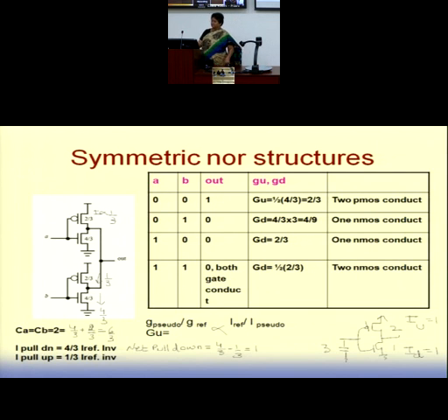In this case, they have chosen the values to be nearly the same as pseudo NMOS just to show that it works over here. So if it is taken as 2/3 and 4/3, and this is also 2/3 and 4/3, we are deviating from mobility ratios. A static CMOS inverter is designed in the ratio of 2:1. We are deviating because we want the symmetric logic to work.